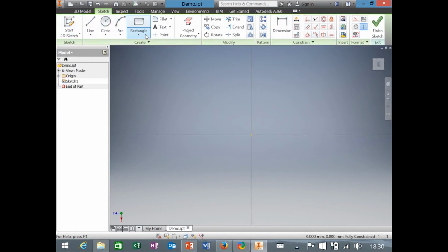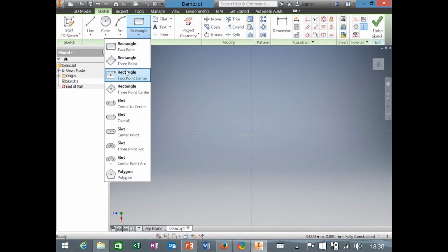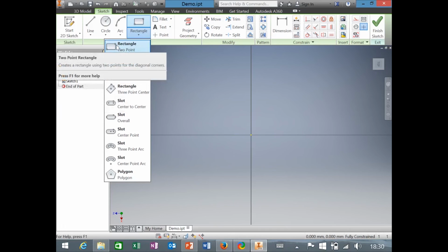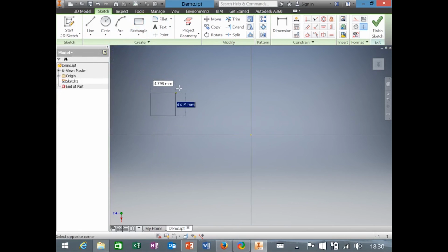Now, I will place a rectangle. And I'm going to choose a different option for how to draw it. So this option allows you to draw like corner to corner, like that. But we want to center it. I just press Control-Z to undo. You want to center it in the view. So we'll center it on the origin.